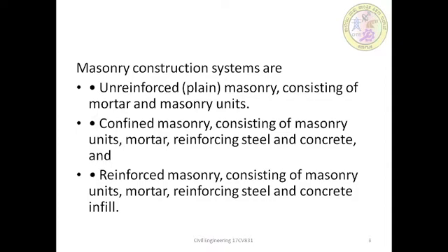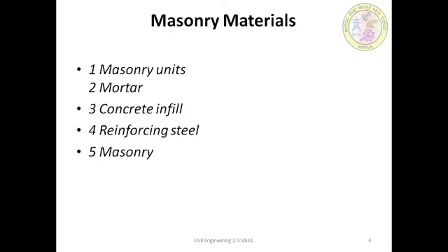Because of the specific characteristics of each constituent masonry material, especially masonry units, it is not easy to predict the mechanical characteristics of the specific masonry type by knowing only the characteristics of its constituent materials, mortar and masonry units. Therefore, for each type of masonry, it is important to carry out experiments to correlate the strength characteristics of the constituent materials with the characteristics of the masonry.